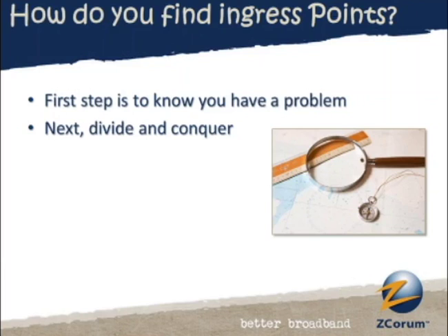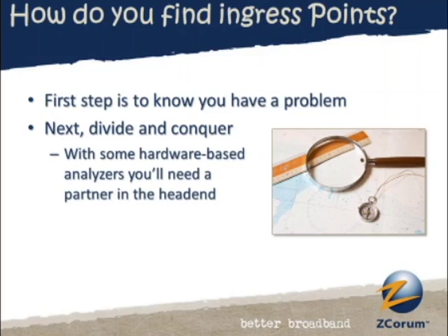Now, here's your bullet point: it can be a little difficult to do that as a solo job, right? Because obviously if you have one guy out in the field, you need somebody else to look at this in the head end. And some operators have actually taken the step of putting a channel onto their downstream and pointing a camera at their analyzer, so you could actually see the spectrum analyzer remotely. But then you need a TV set out in your truck.